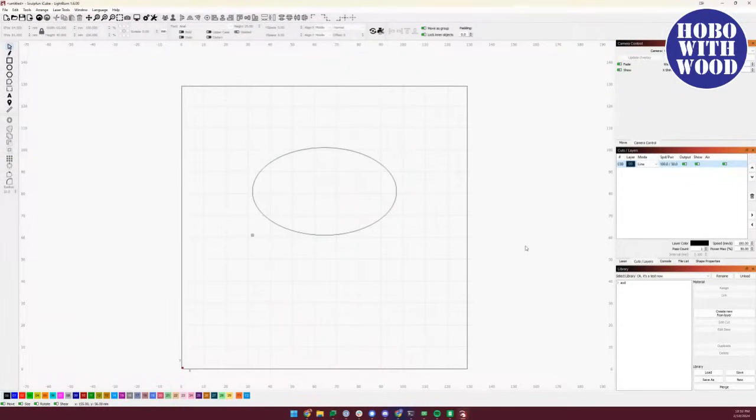For G-code controllers, the funny thing is it's going to be more accurate if it's a bunch of small moves. But if it's a lot of really long, straight, slow moves, it won't be accurate at all. For example, if you wanted to cut out a 600 millimeter square at 5 millimeters per second and you click go, that timer will basically tell you that it's immediately done, because all it has to do is send 4 lines to the controller, and the controller has buffered it and then it's running. But it's not going to actually have the rest of it until it's done.